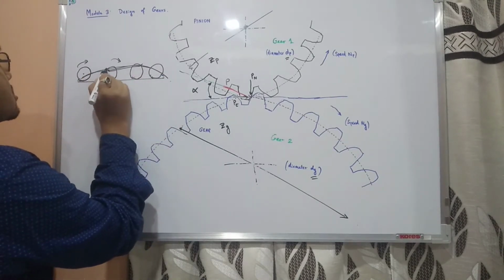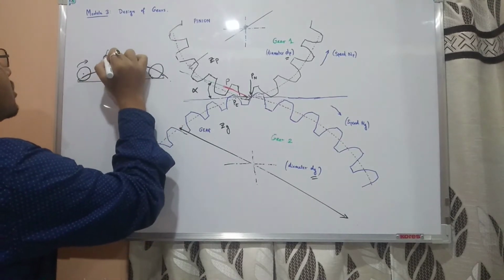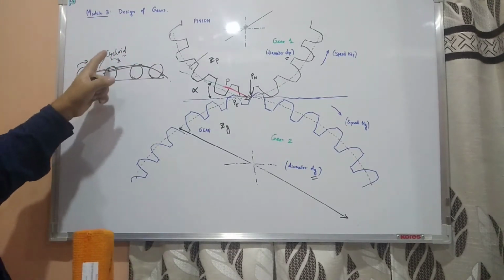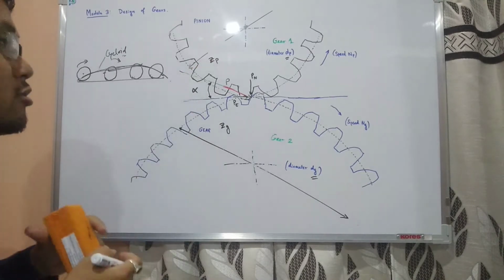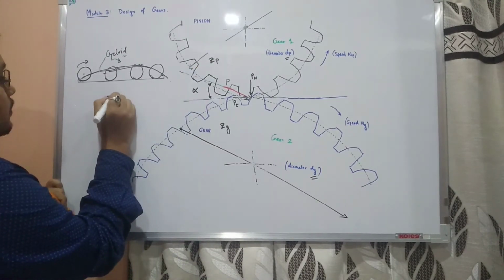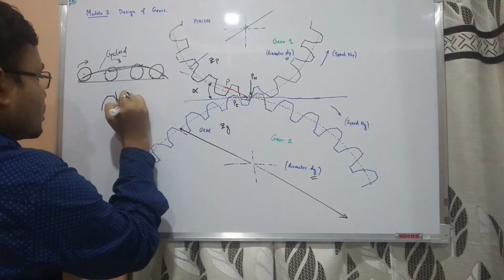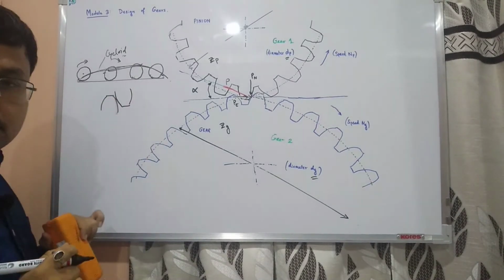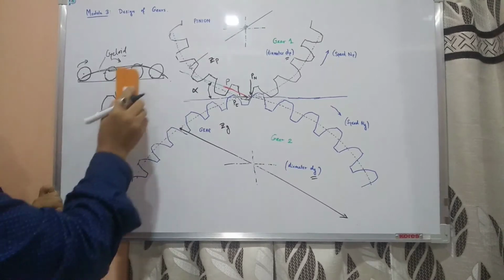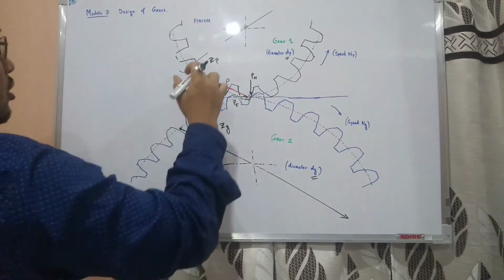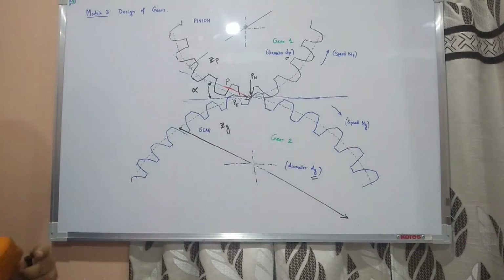Then this curve is called the cycloid. So we can make the gear surface a cycloidal profile also, because it will also provide pure rolling between two gear surfaces. Fine, but we prefer the involute profile, so all of these are involute profiles.